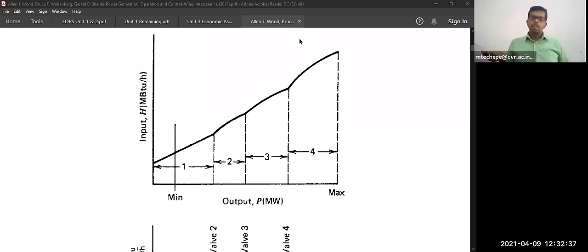After 2 hours of cooling, suddenly they will switch off the air conditioner, and the load will drop. Also, industrial loads have a break at 12:30 to 1:30 or 2 o'clock, a 1 hour or 1.5 hour break when they switch off all the machinery, so the load will be very less.